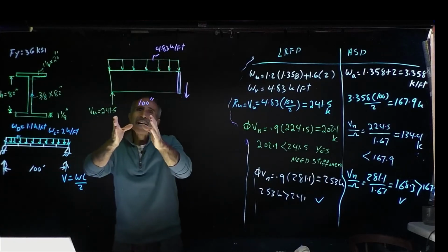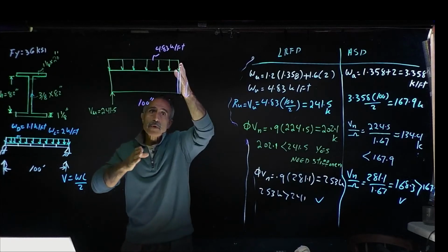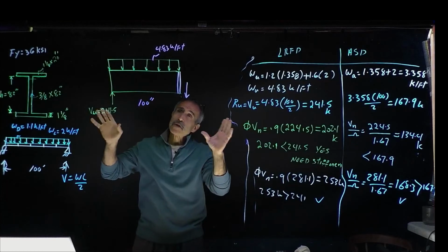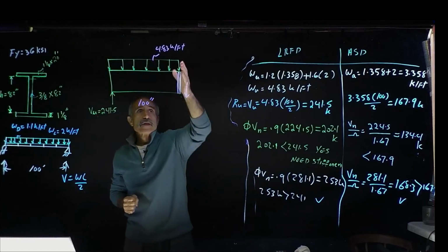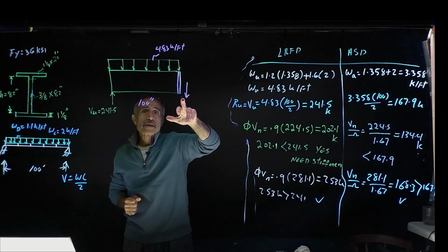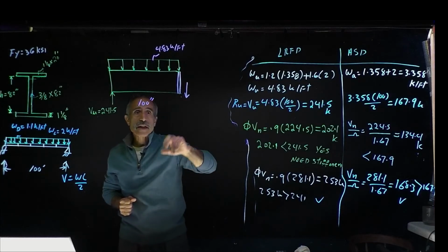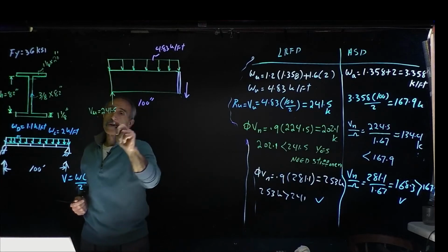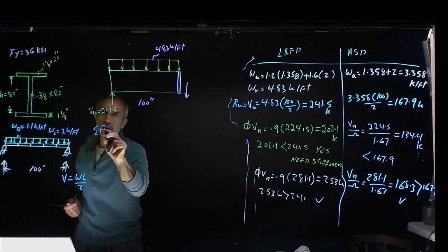So now if I come in 100 inch away, I'm going to put a stiffener in here. So I'm going to make a cut right here. All the structural analysis you did before got to come in handy here. So cut the beam, we want to find out what is the shear capacity here. So let's calculate this shear. Basically, if we do summation of FY equals 0, going up is positive.